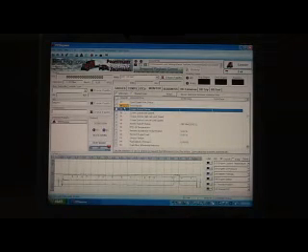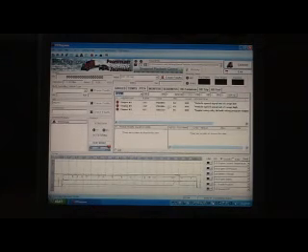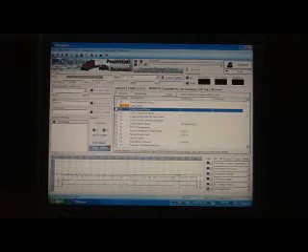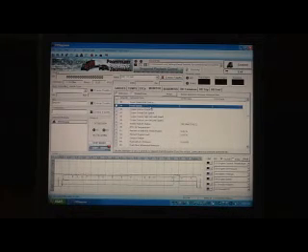If you see a colored box, that indicates that there is a fault on that sensor or on that PID. The fault can be displayed here, for example, vehicle speed signal out of range. In the monitor, road speed, of course, is a fault.